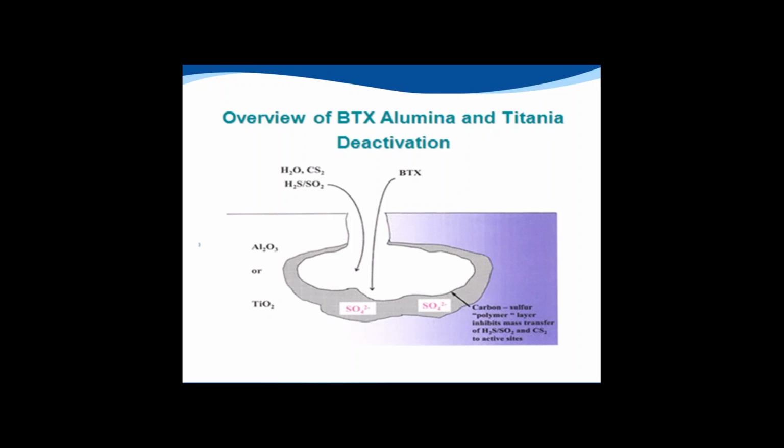When we react H2S and oxygen in small amounts, we have direct oxidation to sulfur vapor. The reaction itself is extremely exothermic. Thus, in order to have a full-scale process where we took all of our H2S and had a direct oxidation scheme with oxygen, it would be hard to generate a process where we could have good control. The original Claus process reacted H2S over a catalyst with oxygen and directly produced sulfur.